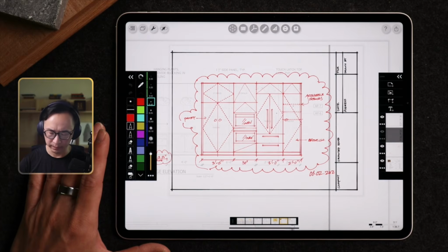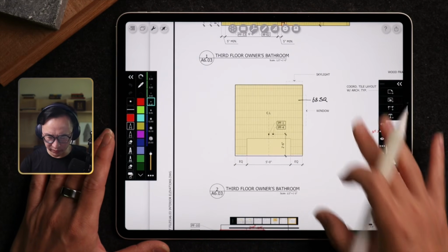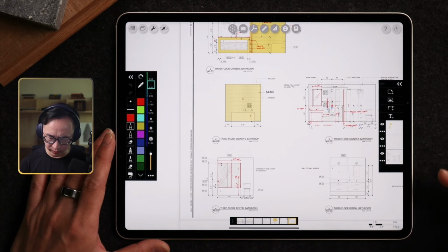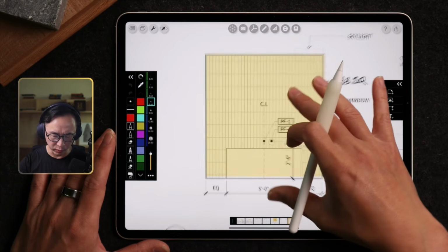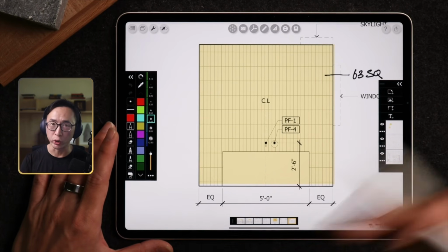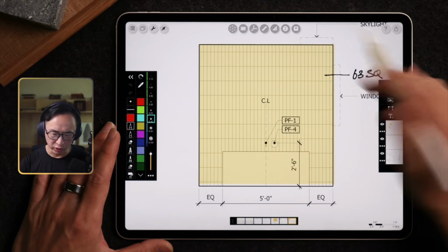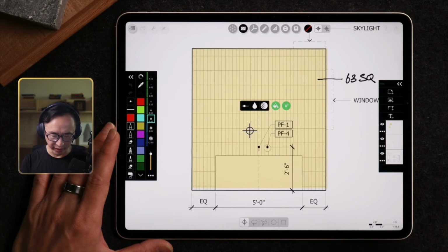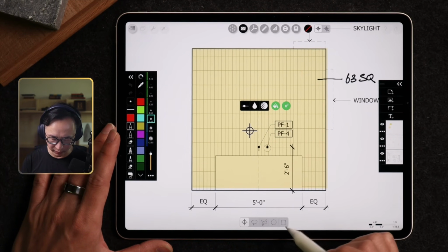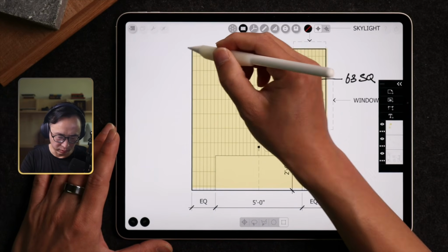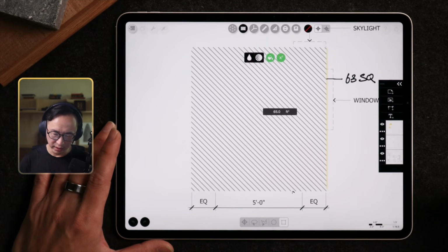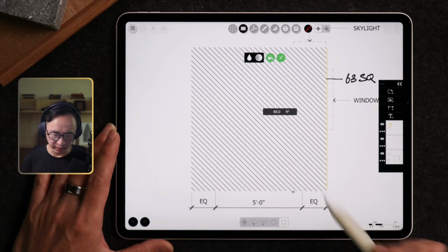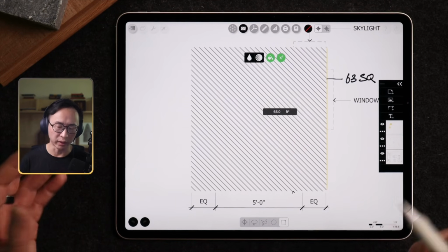to the vendor. And then in the last page of this, let's say you were the contractor, or someone who is ordering the materials yourself, like the tiles, you could actually just do a very quick area takeoff. So if I wanted to find out how many square footage this wall is, by doing a rectangle, this tells me that I have 65 square foot of tiles.